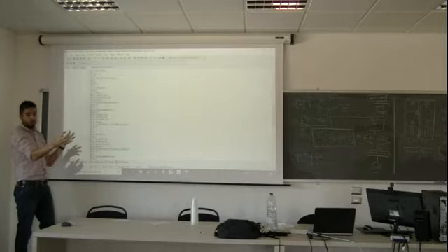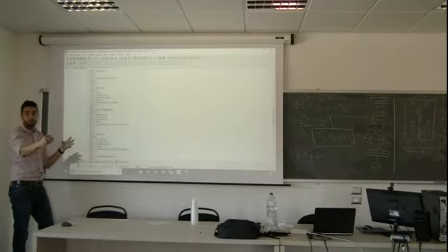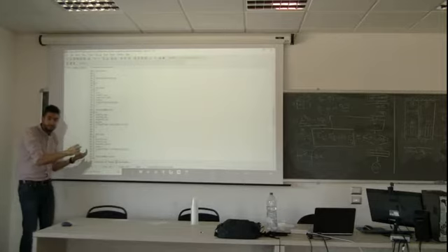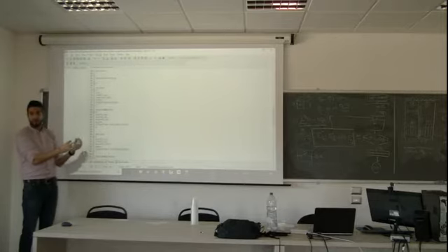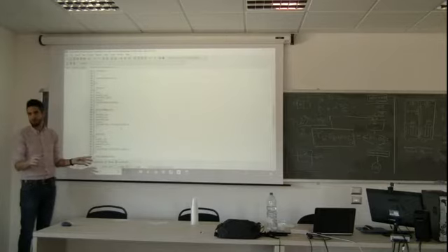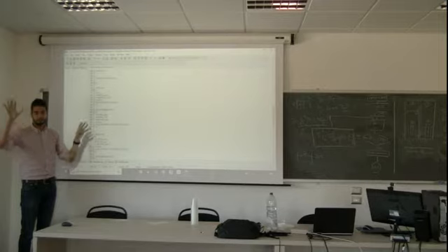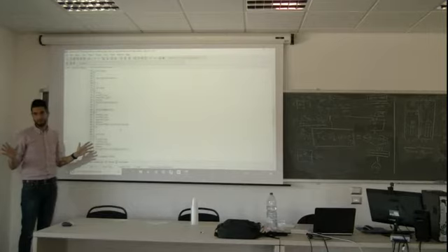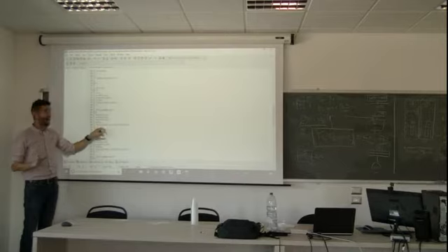But when I want to calculate node number 1, I need the temperature of the neighbors, 0 and 2. For the 2, I have to use the assumption. But for the 0, I have two options: I can use either the assumption or the solution. Never use the solution. Always use the assumption. Don't mix maps of temperatures. If you mix, it can crash.